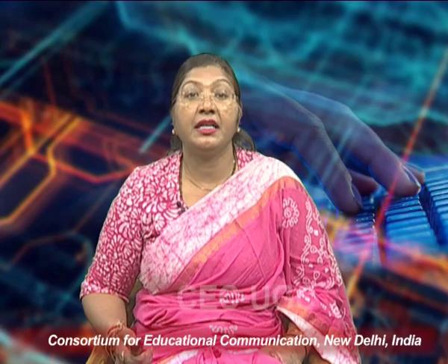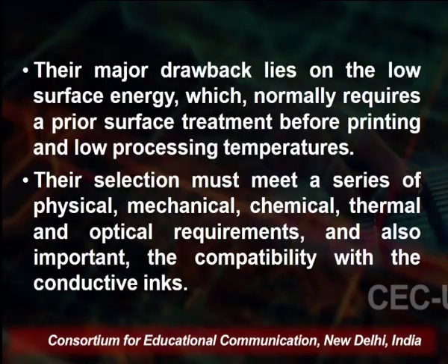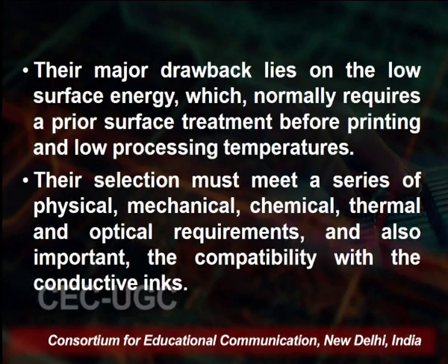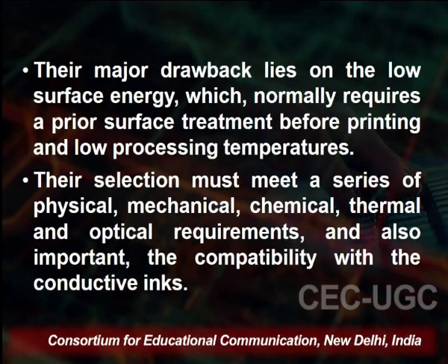Non-reinforced polymers are flexible materials and are more economically processed and give greater freedom of design, providing the studies and increasing intelligent printed electronic applications and able to integrate in complex systems and environments. But the drawbacks, if we talk about, are that it has a low surface energy, which normally requires a prior surface treatment before printing, and a low processing temperature.